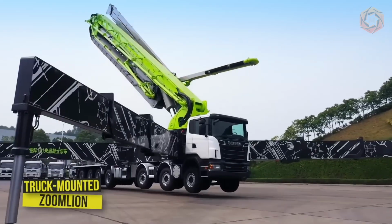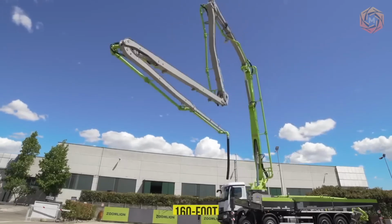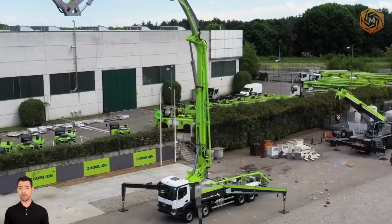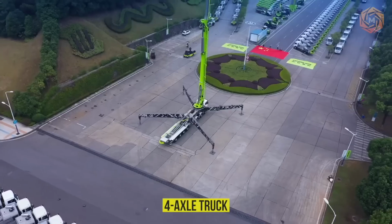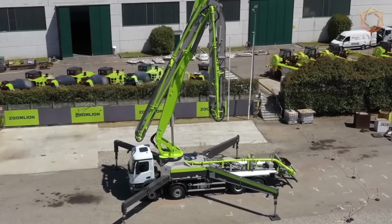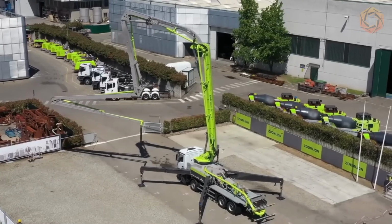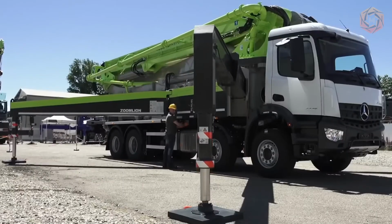The truck-mounted concrete pump from Zoomlion is a 160-foot long truck-mounted pump with high-volume concrete pumping capacity. The maximum pumping capacity is 180 meters cubed per hour, which means a highly efficient design that is mounted on a 4-axle truck with enhanced off-road capability and maneuverability. The hydraulic system is fully automated, and high precision at the production stage guarantees stability and reliability of the overall system. And the one-sided opening of the side outriggers allows safe operation in difficult and narrow areas.